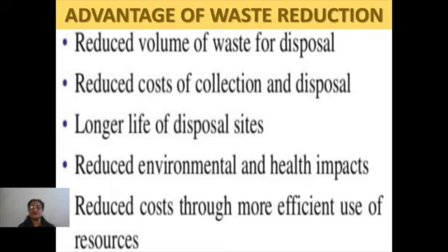Naturally, large amount of waste in its collection, in its transportation, in its disposing of, everything needs more expense. Now, if the total amount of waste which is being generated is very less, naturally it is going to reduce the cost of all that. Then longer life of disposal sites. Then it reduces the environmental and health impacts also. Negative impacts are reduced to a great extent. Then it reduces the costs through more efficient use of resources. So these are the advantages of waste reduction.